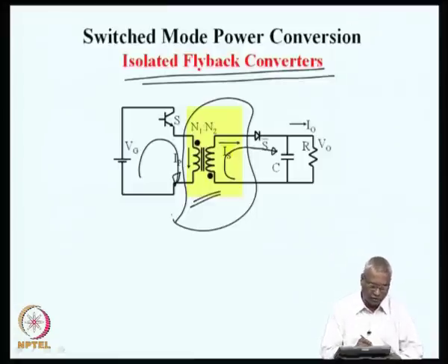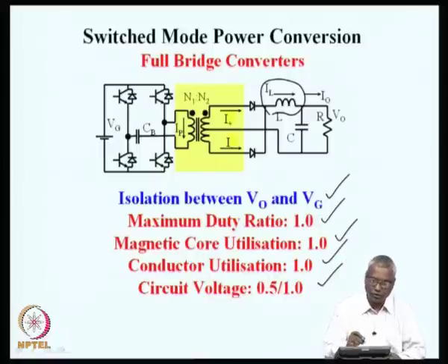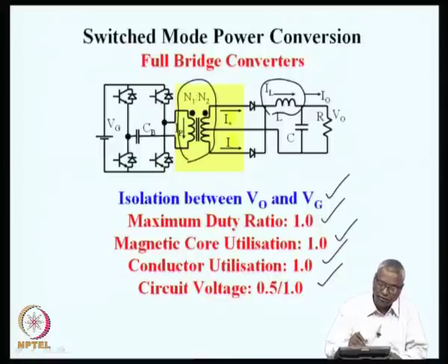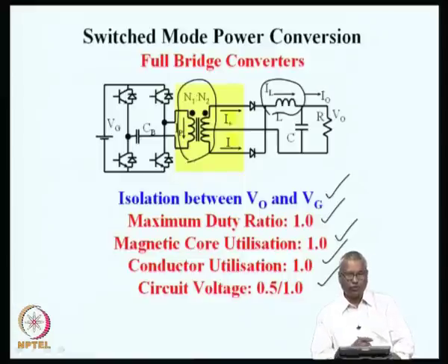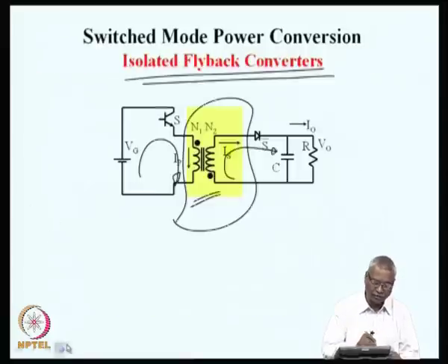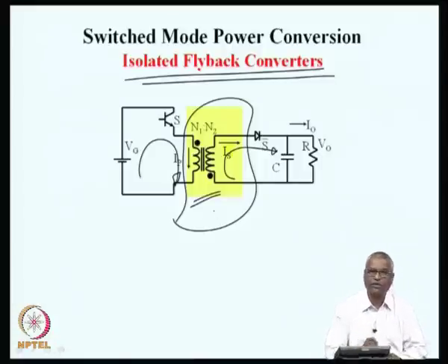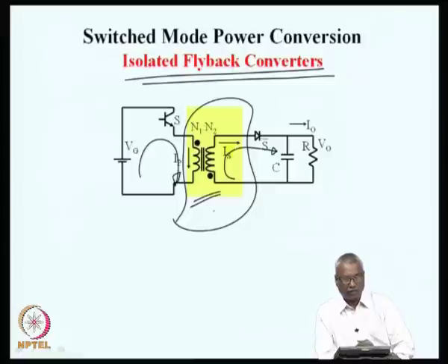In the earlier converters like the forward or any of them, we had one inductor for smoothing the energy flow and another electromagnetic circuit for providing isolation. So, there are two electromagnetic elements, but in the flyback converter, these have been combined into a single electromagnetic structure. This is working both as a transformer and also as an output filter.